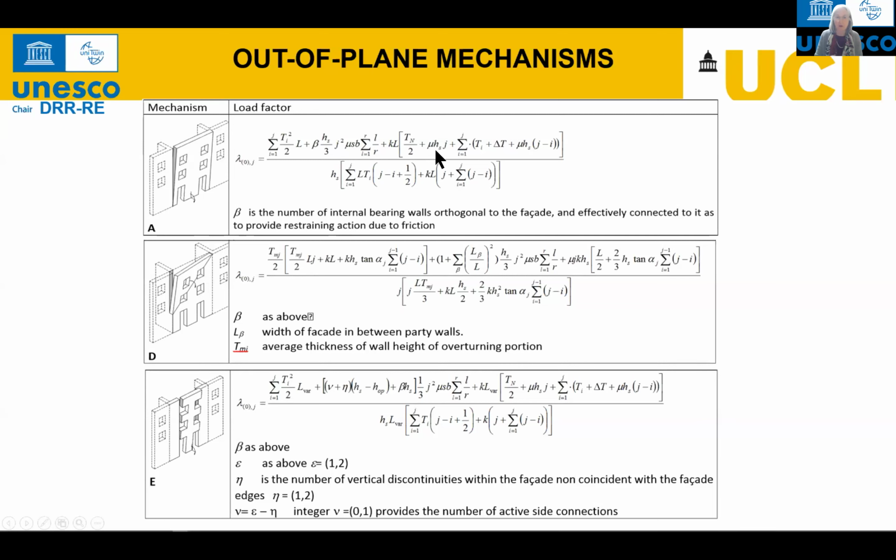And so using limit state analysis, what we do is predetermine a mechanism for the facade, and then we compute all possible solutions depending on the number of stories that are involved in that particular mechanism. These equations are then included in an algorithm and programmed in Visual Basic and Excel so that we obtain the results. And for each of the mechanisms, we consider the minimum case.